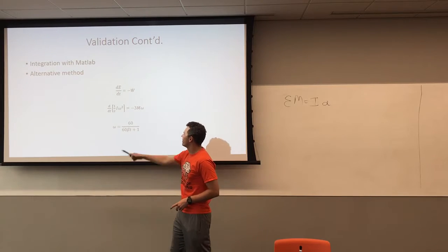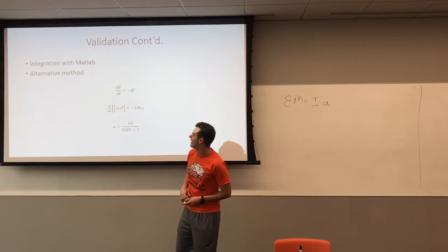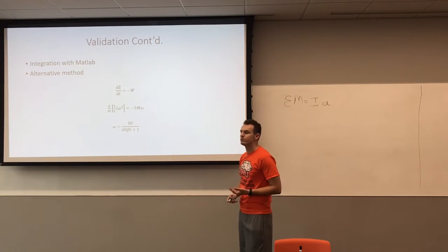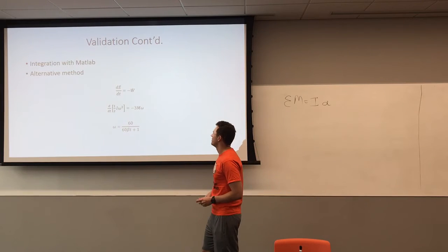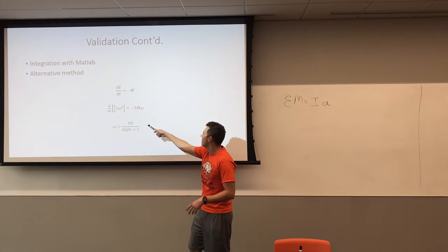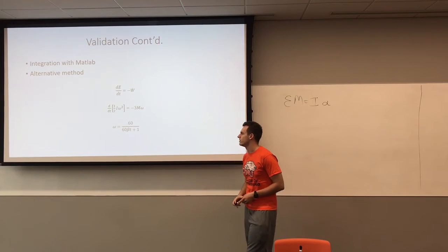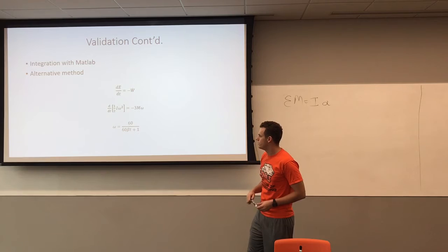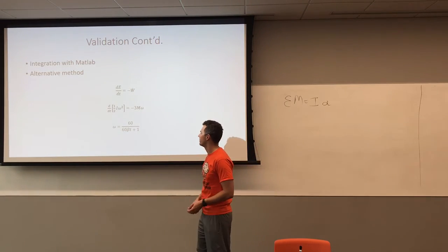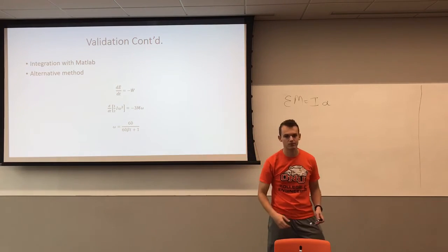So we set up our kinetic energy equation, which is 1/2 the mass moment of inertia times the rotational velocity squared, and it's going to be equal to negative 3 for 3 blades times the moment created by the drag times the rotational velocity. And when we carry that equation out, we end up developing the exact same differential equation that we started with in the first place.